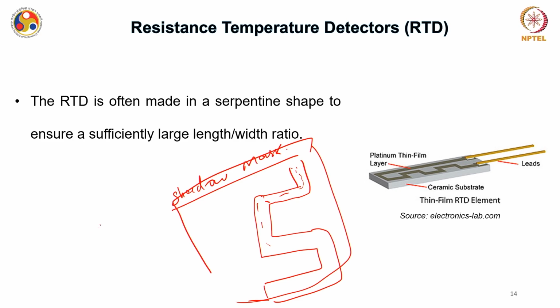Okay. And this is say part of a bigger aluminum sheet or a stainless steel sheet. Now in the deposition system you have a wafer kept like this. And in between you have this patterned shadow mask, right. And below you have this crucible in which you are evaporating, say, aluminum or nickel for making this serpentine thing.